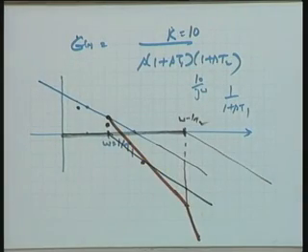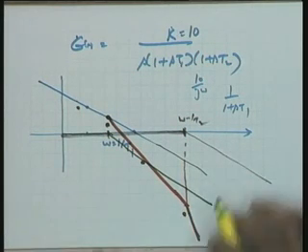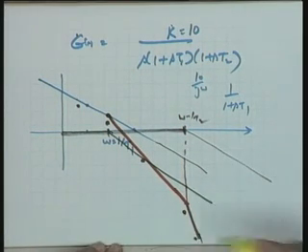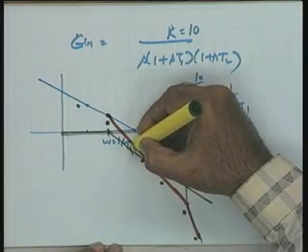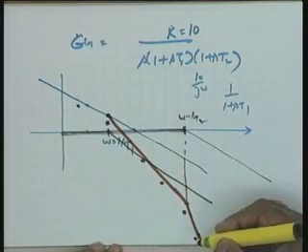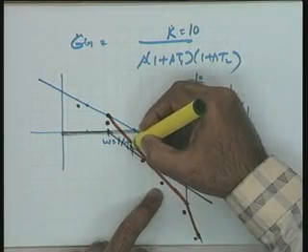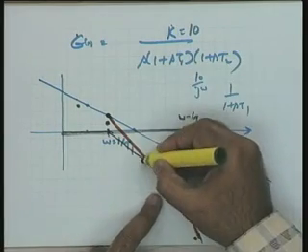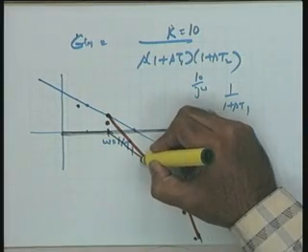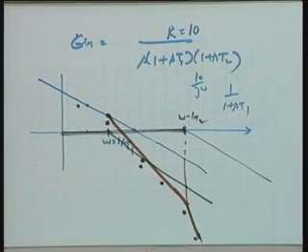Note interestingly, if I take now another point, it is 3 dB down here. 1 octave above is here, 1 octave below is here, 1 octave below could be here also, it does not matter, it is just the algebraic addition. It does not mean that 1 octave below cannot cross this particular point, or it cannot be at the same point. It can be, and if it is at the same point, it becomes 2 dB down.